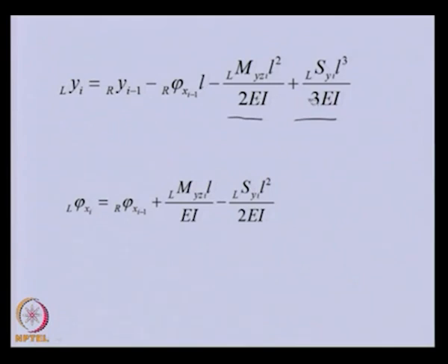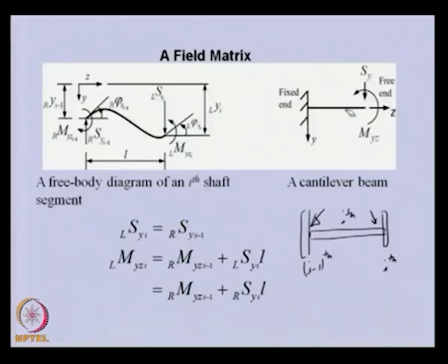This is while considering the shaft as flexible and the left-hand support as rigid, that means the cantilever case. Now, in the second case, we will consider the shaft as rigid and then give these two displacements, y and phi, to this end of the shaft, which in the second case we are considering as rigid.